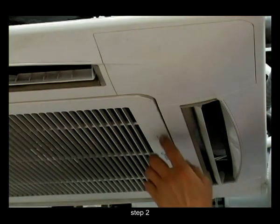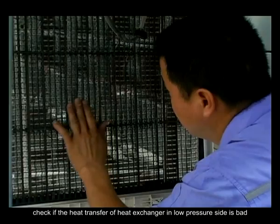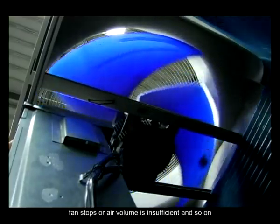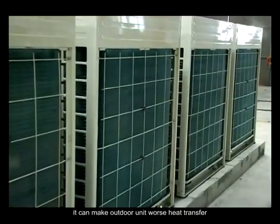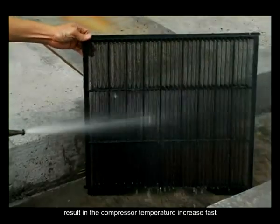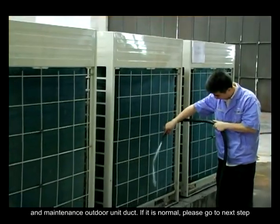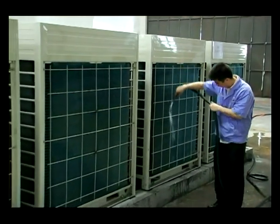Step 3. Check if the heat transfer or heat exchange in low pressure side is bad. If heat exchanger or filter becomes dirty, fan stops, or air volume is insufficient, and so on, it can make outdoor unit worse heat transfer, and the working condition is terrible, result in the compressor temperature increase fast. If it is the problem, please wash the heat exchanger and filter, and maintenance outdoor unit duct. If it is normal, please go to the next step.